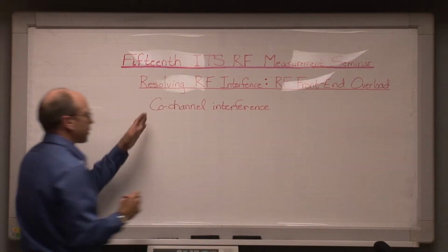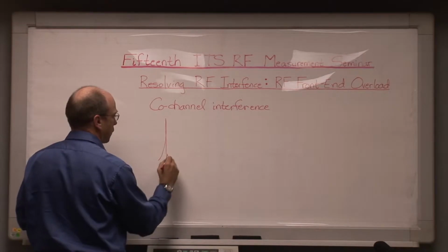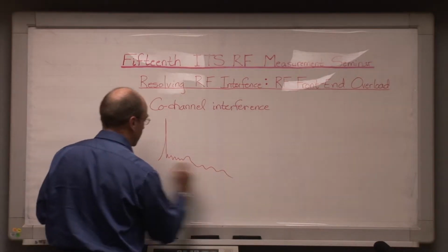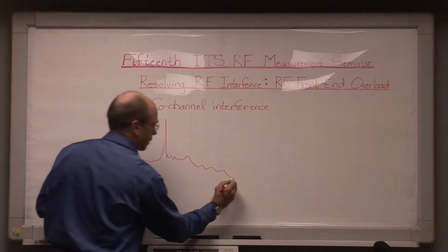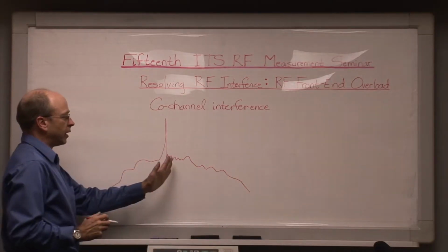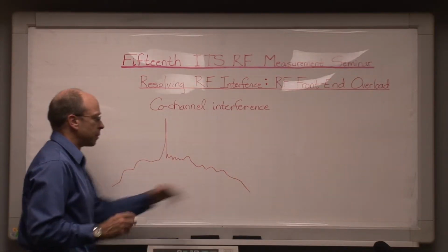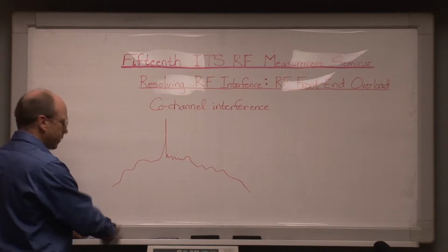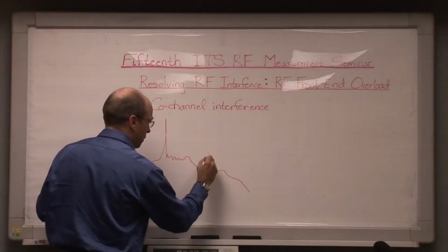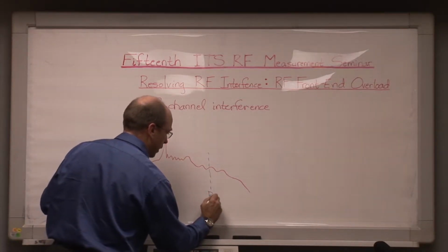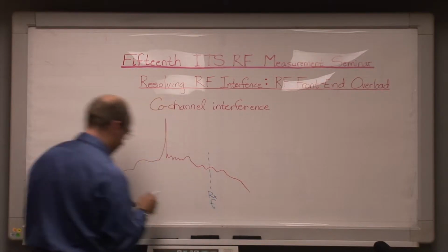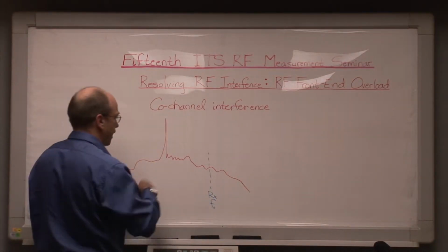And this, of course, is a case where a transmitter is operating at some frequency and it produces certain levels, typically of out-of-band or spurious emissions, and a receiver is running at some frequency over here that we'll call the receiver frequency, where this is the transmitter frequency.